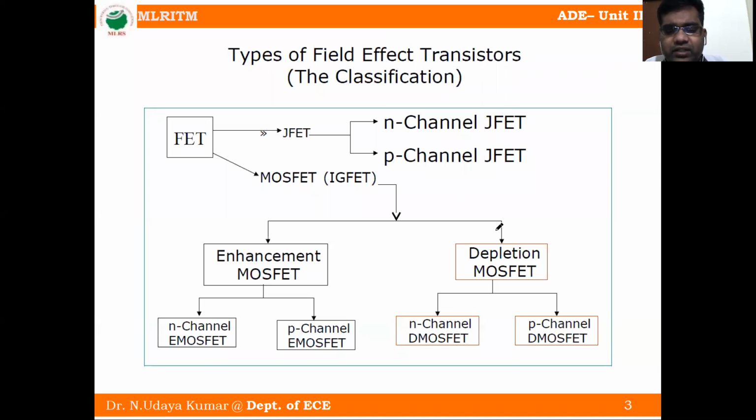Electrons, which are the majority charge carriers in the n-type bar, enter the bar through this terminal. Always remember, the source terminal is always connected to the negative terminal.